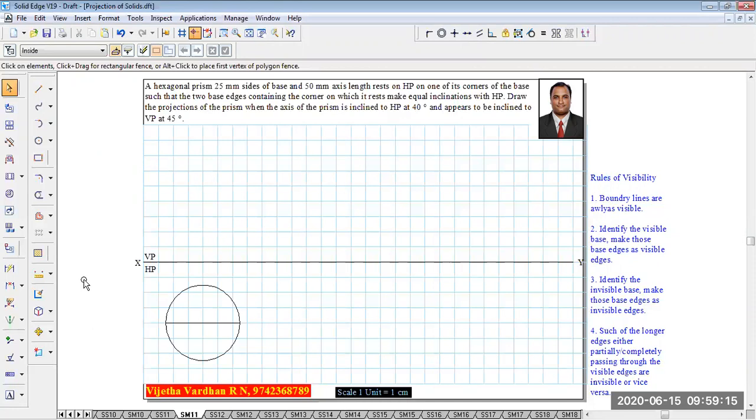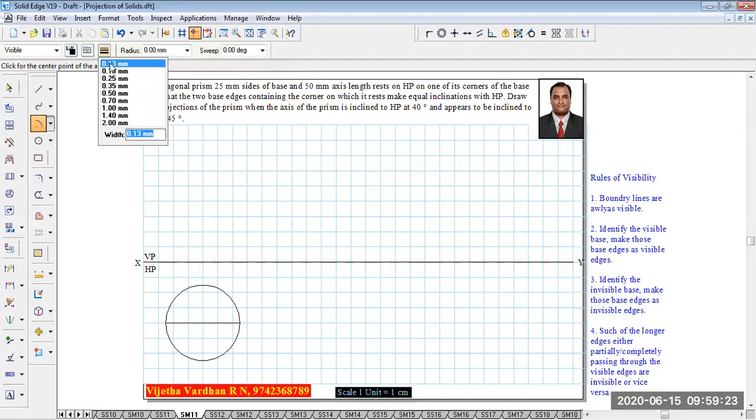Now, to complete this circle into a hexagon, you are supposed to follow the procedure. Now, I am going to show it to you. Without changing the radius of the compass, keep the compass at the left-hand side, and then without changing the radius, I told you, draw an arc like this.